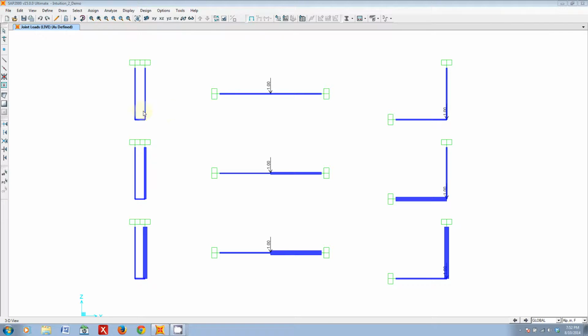What do I mean by stiffer members? Well, a stiff member usually is one that's just thicker, bigger, heftier, deeper. Longer, no, not longer. In the case of an axial rod, a stiffer member is one that has a larger cross-sectional area, and for a beam, a stiffer member is a beam that has a greater depth. So I'm going to go through a couple of examples.